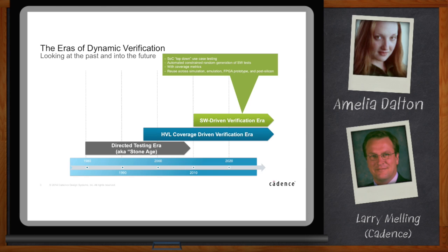So we really want to apply what we've learned in metric-driven verification at the SOC level and say, let's create a top-down use case, but let's make it controlled from a metric basis. And let's think now about how we have to constrain not only random data production, but also the control flow. Because we have to see things can happen in parallel, serial, you never know.